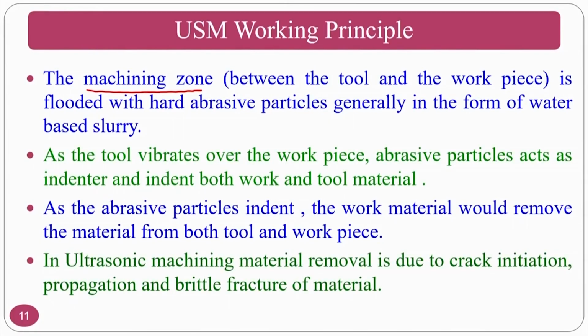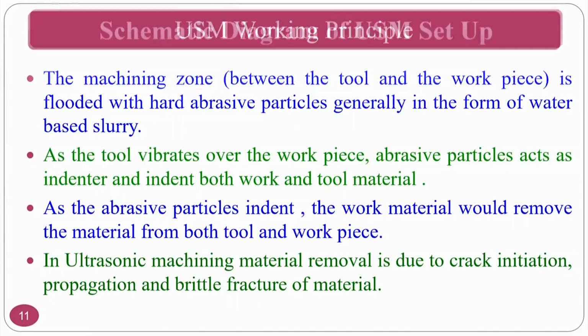So, the abrasive particles go and hit the workpiece. If the workpiece is brittle, the brittle fragments will come out by brittle fracture. The material removal in ultrasonic machining is due to crack initiation, if the workpiece material is brittle, and propagation and brittle fracture of the material.